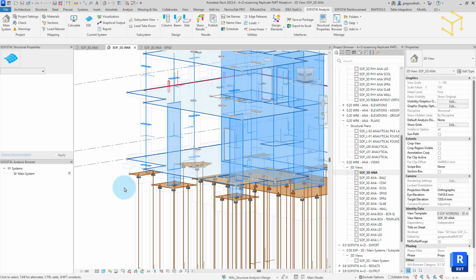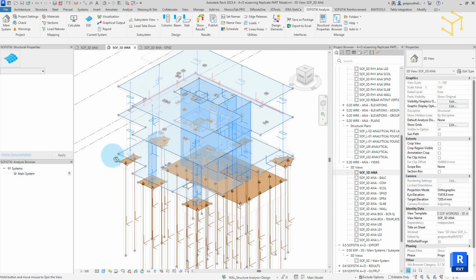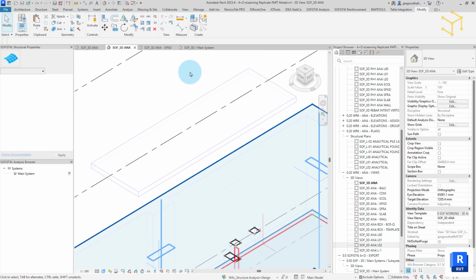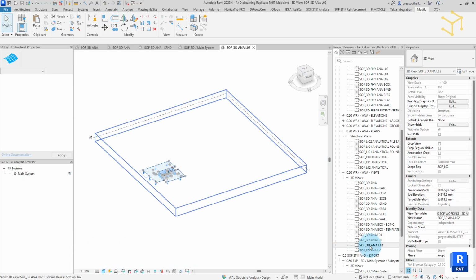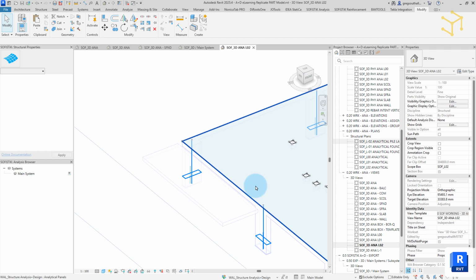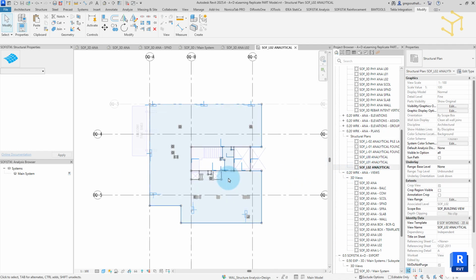This completes the pile generation and naming exercise. For the balconies, two common types are encountered in a typical concrete frame. These are thermally isolated balconies with either 1. A continuous support via something like a rebar continuity system, or 2. Discrete support points with cast-in embedments into the slab. Balconies on this project represent the latter, i.e., discrete cast-in embedment type.